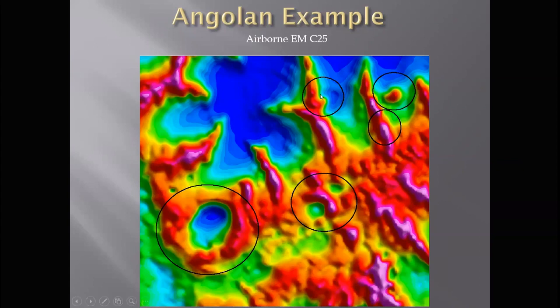These guys don't show at all. This guy's saying, heck, well, I've just got a bit of river sediment on top of me. That one shows a little bit of an electromagnetic high. This one shows two circular features with a river going through the middle. So you've got a host of different responses, just like you did in the mag. It's so useful to be able to view everything. Mag, EM, tau, channels, everything. We've got so many different responses.